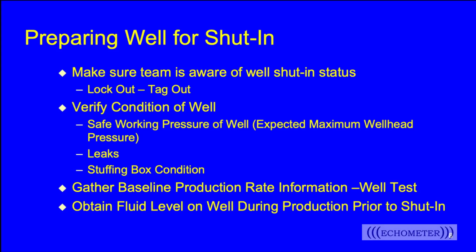You also want to verify the condition of the well and make sure that your pressures won't exceed the safe working pressure of the well. You'd like to make sure there's no leaks, and that your stuffing box on a rod pump well is in a good enough condition that it won't leak as the pressure on the well increases.